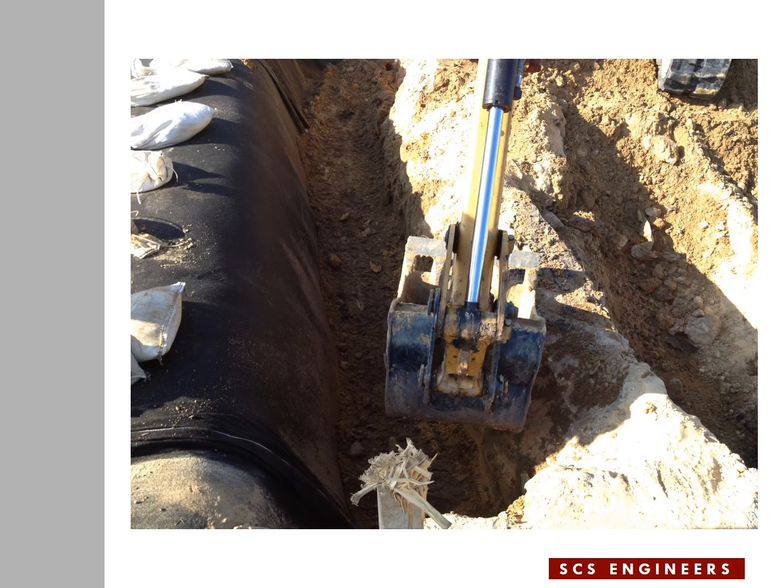At this stage, the backfilling of the anchor trench begins. So we have 3 geosynthetic components go in the anchor trench before the backfilling begins: the lower geogrid, the textured geomembrane, and the composite. And the backfill gets compacted using either the hand tamper compactor or the back of the backhoe bucket.